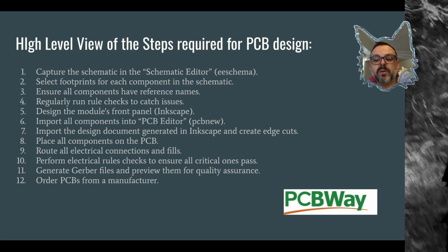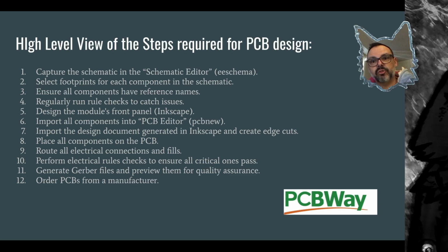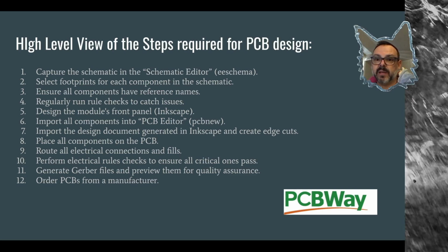So when we get to near completion, since we're making a multi-board synth here, or module here, I will walk you through what I do to create this, and the outcome of that will be Gerber files for each board. Since we're likely going to split it into two boards, a control board and a main board, and then a panel, we'll have 3 sets of files.